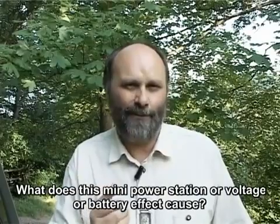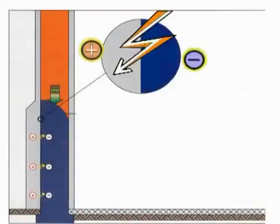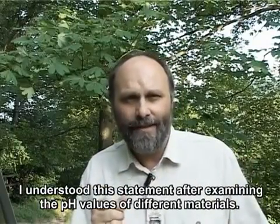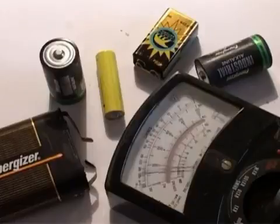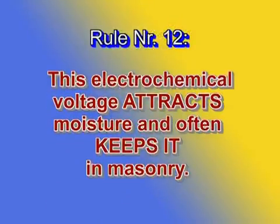What does this mini power station or voltage or battery effect cause? It attracts moisture or retains it artificially. According to common parlance, cement attracts moisture. I understood this statement after examining the pH values of different materials. Different materials, especially when walls are slightly moist, create a positive pole in one material and a negative pole in the other, like a battery. This obviously results in a measurable voltage. The higher the pH differences between materials, the higher the voltage. Rule number 12. This electrochemical voltage attracts moisture and often keeps it in masonry.